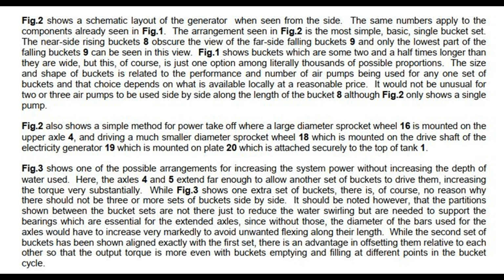It should be noted, however, that the partitions shown between the bucket sets are not there just to reduce the water swirling, but are needed to support the bearings which are essential for the extended axles, since without those, the diameter of the bars used for the axles would have to increase very markedly to avoid unwanted flexing along their length. While the second set of buckets has been shown aligned exactly with the first set, there is an advantage in offsetting them relative to each other so that the output torque is more even with buckets emptying and filling at different points in the bucket cycle.